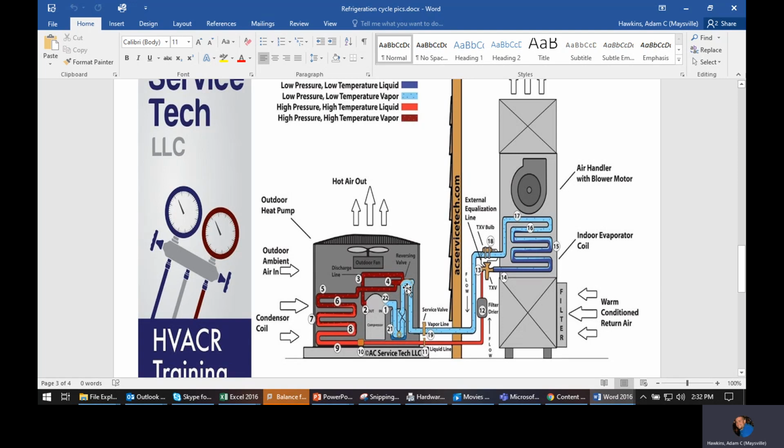So if we have, and I'm just making up a number here, let's say 40 degrees discharge superheat. So let's say the line is 140 degrees and my condensing temperature is 100. I'm just making that up. If I have to remove 40 degrees, then that means I have to remove 40 degrees of sensible heat before I can ever start to condense. Remember, I don't do any work really through the sensible. So I have to get to that latent as quick as I can, because that's the thing that's going to really start the work. So in that condenser, as soon as it desuperheats, it's going to start to condense.